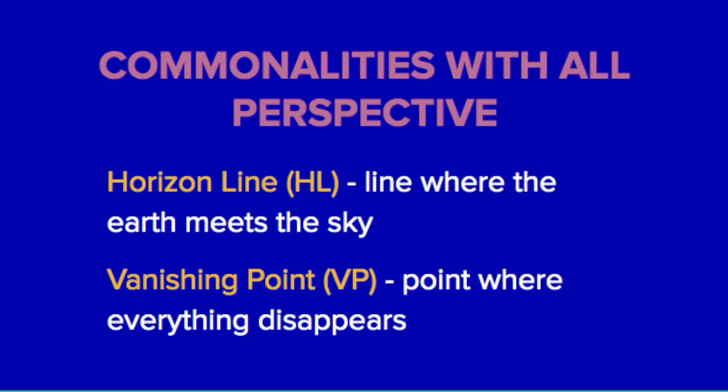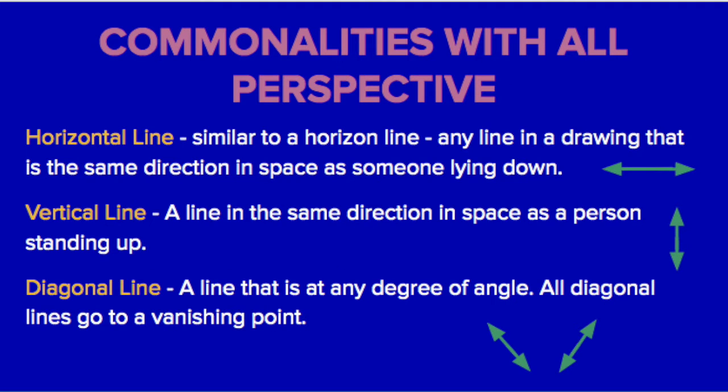of perspective you're drawing. Items drawn in perspective will have a vanishing point, or where the object seems to disappear. Additionally, there are three main types of line when you're drawing architectural drawings like what we're going to do for the hallway drawing or for a building. Those line types are vertical, horizontal, and diagonal. Any line that is diagonal should be going to a vanishing point.